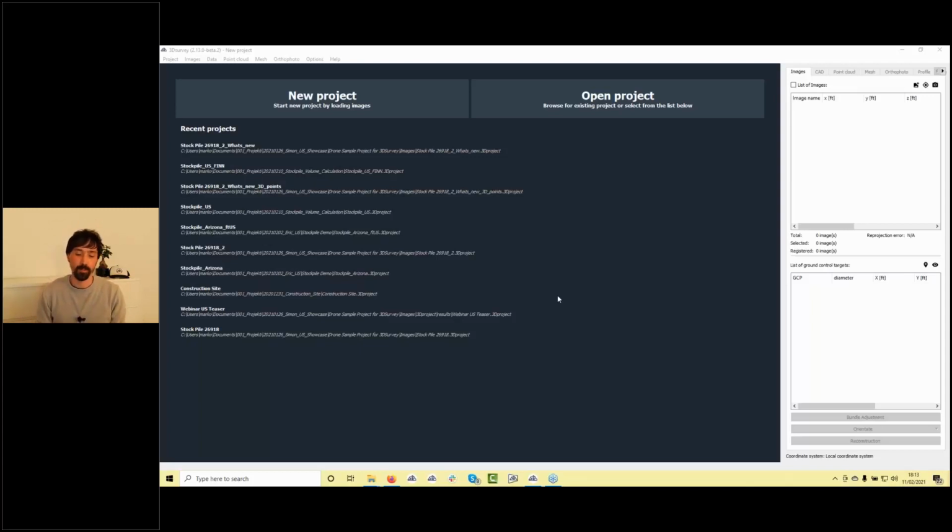I know the P1 has more megapixels, but if you fly up to 100 meters, you don't need them. With the Phantom 4 RTK at 80-meter height, you get a resolution of 2 centimeters, and this is more than enough in most cases. If you'd like better accuracy, you can fly lower.